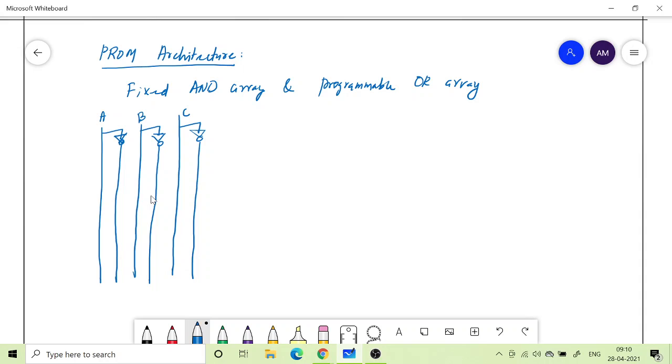If I do it in a symbolic fashion, what we usually do is basically draw a line like this, and then we are basically looking at the circuit inside a decoder. Okay, so this is same as the circuit that is inside a decoder. So for example, you need connections with A bar, B bar and C bar. Okay, so that is going into an AND gate.